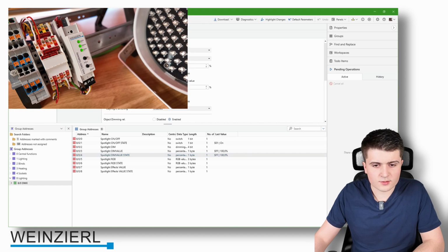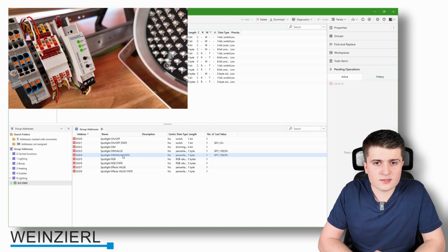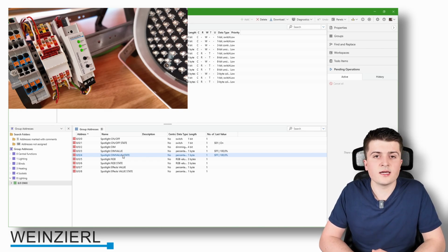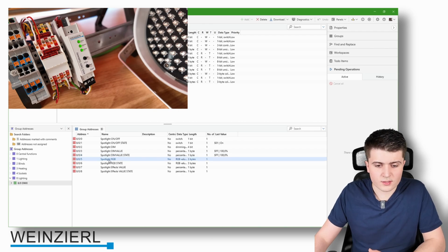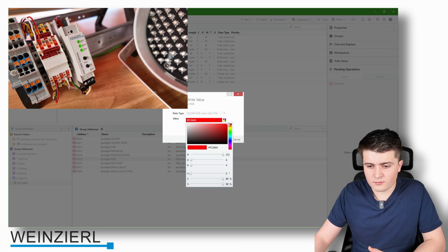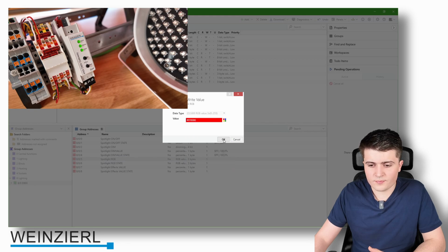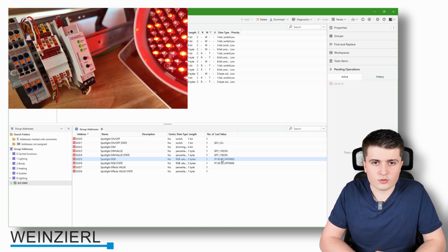If I take a look into the dimmer and the absolute object, here we have a fade rate of 4 seconds set up. Now here it states that the light is at 100%, but if we take a look at it, it is dark. And that's the case because I haven't set up a color where the spot should turn on to. So therefore, let me quickly set the color here, for example, at the value red. I click on OK, and now we can see that the light goes on the value red.